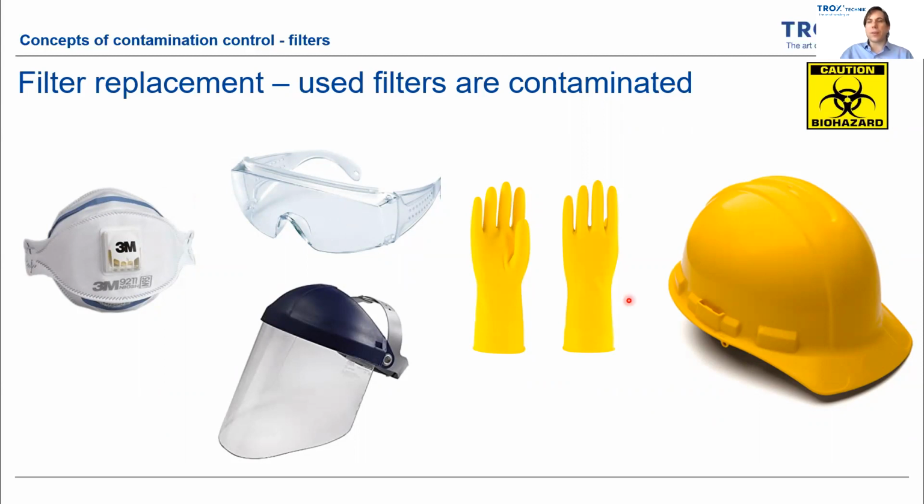Well, this filter is retaining all this matter, particles and microorganisms flying around. So at least we should use a mask, gloves, put it inside a bag, and then send it for disposal. I added the helmet because in some of the big installations, we go to the machine room, and it's quite common that people hit their head on some tubes and structures.